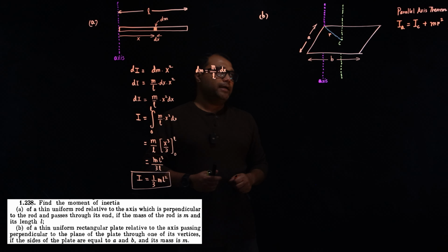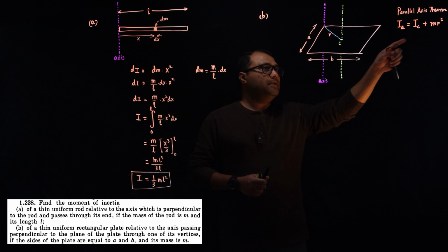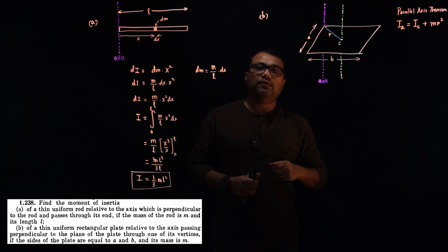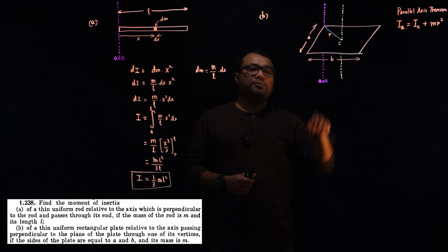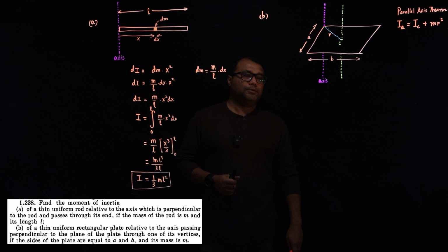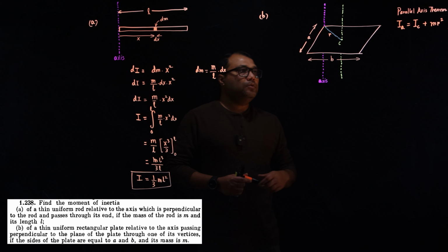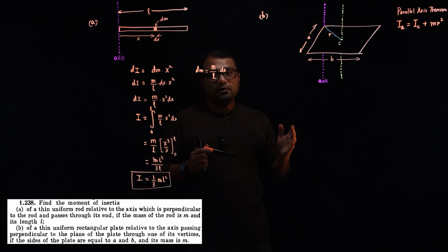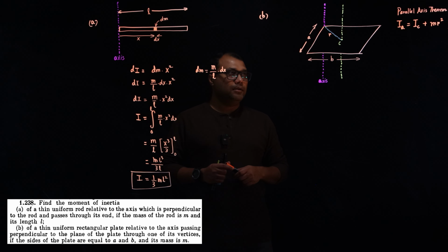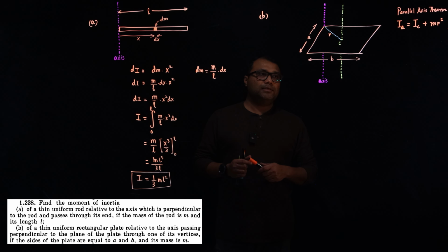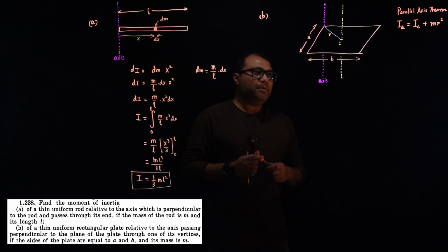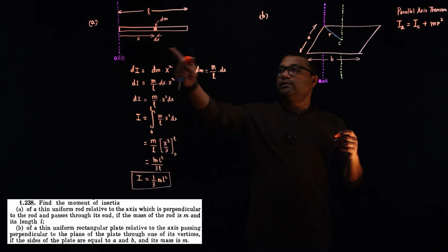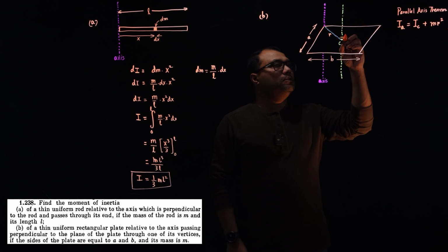So I just rewrote that nicely. So r is the distance between those two parallel axes. One of the axes has to pass through the center of mass and the other axis has to be parallel to that axis. Okay. Now, do we know the I of a laminar rectangle about its center of axis? Yes, we know that, but maybe I should show you how to derive it, using this result maybe. Okay. So let's look at that.